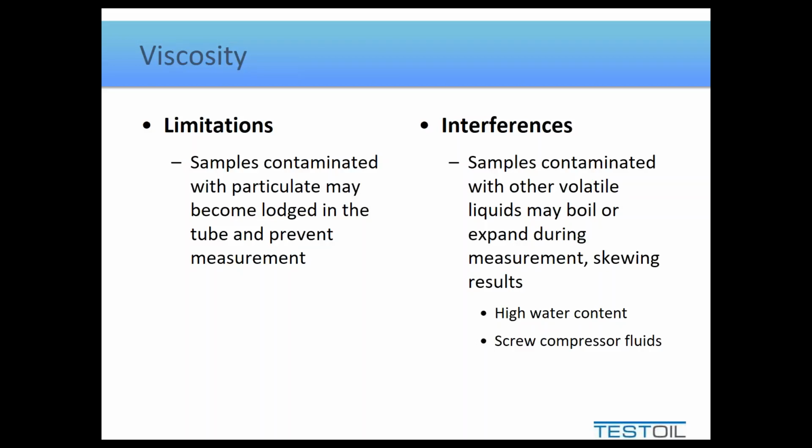So where we tend to see this is in samples with particularly high water content, or very commonly in screw compressors, only because screw compressors tend to push whatever medium it is they're compressing into the lubricant, and the samples become quite gas-filled. Now again, as I said, if I have a sample that's got such high water content, it starts affecting one of my tests, that's my problem.